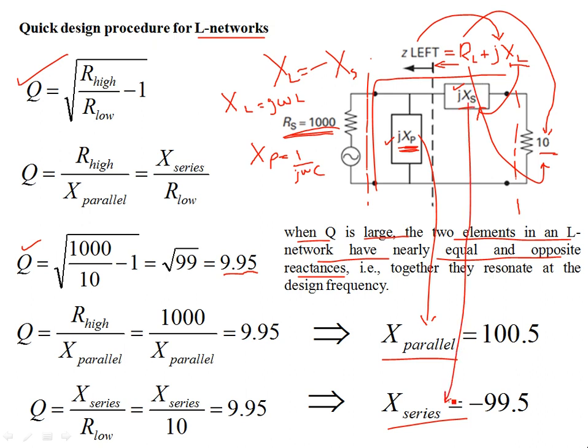Isn't that right? A very high Q circuit means you're going to have a very narrow band match, and the bandwidth is small. The 3 dB bandwidth is small. The peak is large, so the matching could be something like this. If this scale is versus frequency, this is a high Q matching. This is the amplitude or the power transfer. So that's your design frequency at which the maximum power is desired to be transferred.